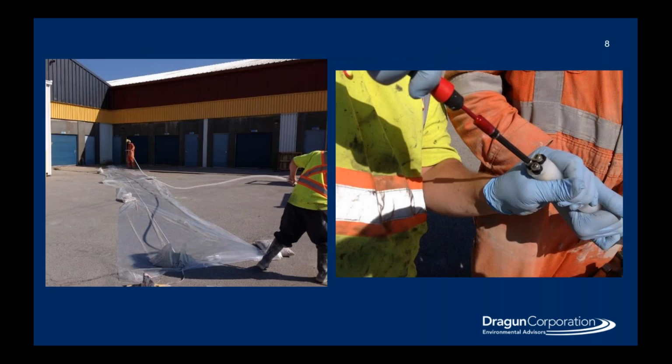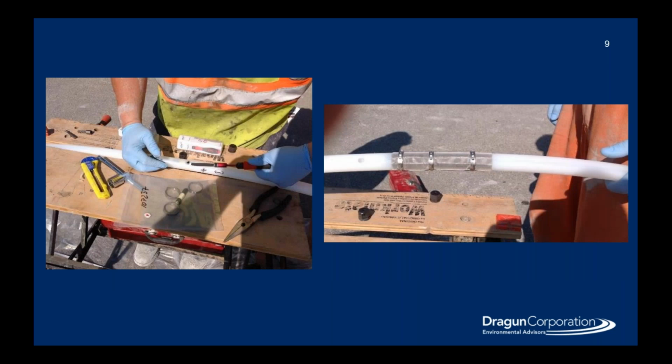A couple more pictures of how this is implemented. So it comes in a big roll, and you can see on the left-hand picture them rolling the tubing out and cutting it to the right length. And then on the right-hand picture, they're installing some hardware in the 3 channels. And then here you can see a picture of the installation of a screen, and you can see it's right in line of the tubing, and you can have multiple screens, obviously within a single set of tubing, to be able to take samples from different depths within the borehole.